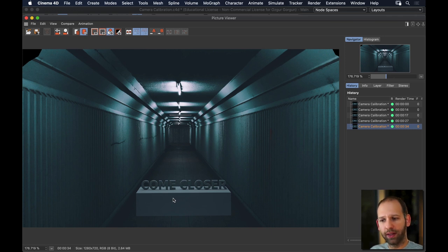And the reason for that is that the floor, which is part of the room model, is using a texture that's got the luminance channel turned on. So it's acting as a light source, which means it cannot receive any shadows.